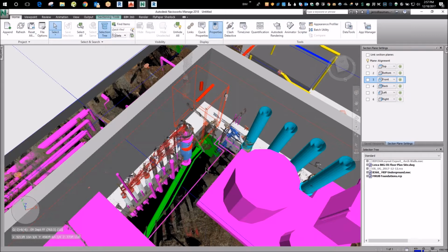And of course, the less we have to scan, the better. So if we do it in small chunks or whatever, but realistically, we'd be out there for 3 to 4 hours to do all those scans, and usually 2 of us would come and survey them. Come back, it's about 4 hours to process that many, 12 to 14 scans, and then bring it in and get it set up in the model.